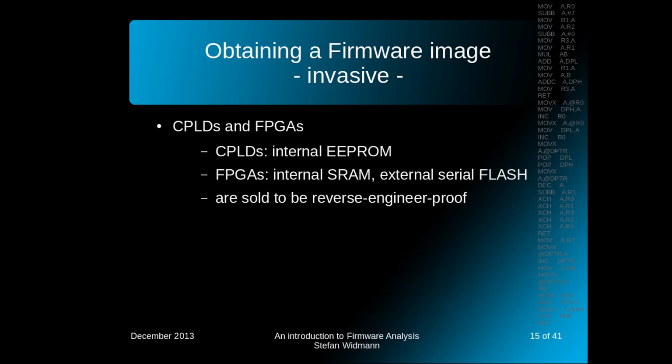So, just for a matter of completeness, I'm mentioning CPLDs and FPGAs. You know, CPLDs are built up using internal EEPROM. FPGAs, field programmable gate arrays, have internal SRAM and an external serial configuration flash. Some years ago, they were marketed as being reverse engineer proof. Okay, yeah, maybe. There's a talk tomorrow, same time, I think, Saal 2, about taking a closer look at FPGAs.